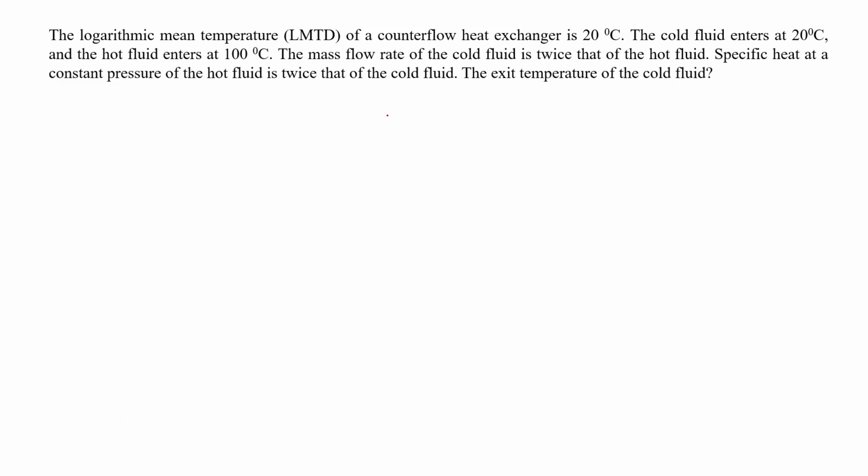The cold fluid enters at 20 degrees Celsius. The hot fluid enters at 100 degrees Celsius. The mass flow rate of the cold fluid is twice that of the hot fluid. Specific heat at constant pressure of the hot fluid is twice that of the cold fluid. The exit temperature of the cold fluid we have to find.